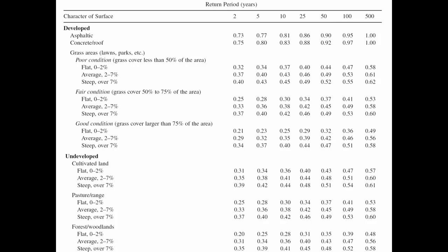Why? So if it's flat, there's pooling, yeah, and if you've got a pool of water, that's more of a driving force to get the water infiltrating. But if it's sloped, then it's already moving, it's got momentum, and there's less of a tendency for it to infiltrate down into the soil. So that's the other trend we need to be aware of: steep areas tend toward less infiltration and more runoff.